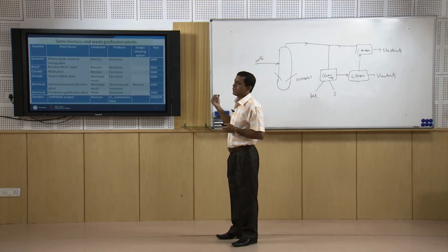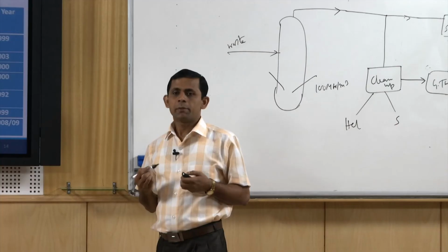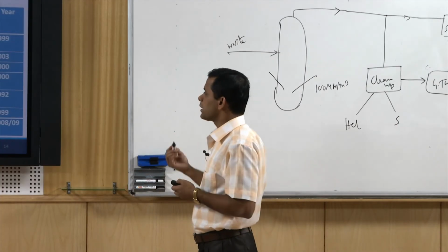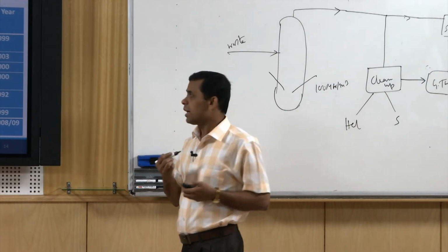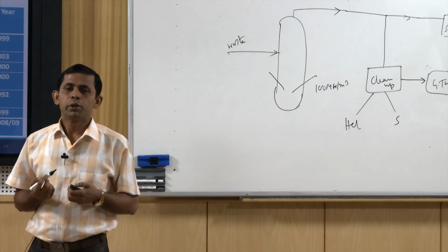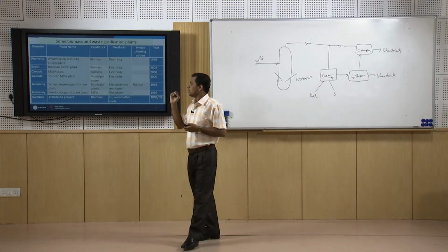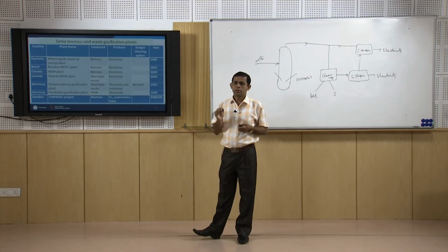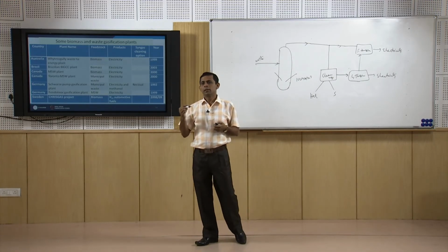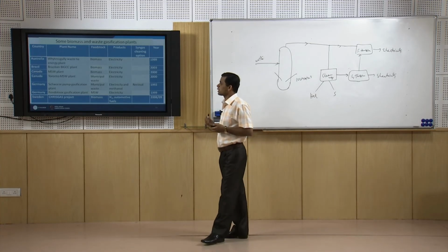So, to make the process competitive, the process should be of very high capacity, the production capacity should be very high, but biomass and waste gasification process produces less amount of syngas. So, less amount of syngas cannot be processed economically in comparison to other processes.